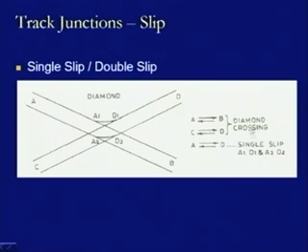So, in the diamond crossing, as we see, it is also being written, the movements are either from A to B or back, that is from B to A, as well as from C to D and back, that is from D to C. That was the type of the movements available in the case of the diamond crossing, but in the case of a single slip, we also have A to D or D to A. So, it means the number of movements have been increased in the case of a single slip.